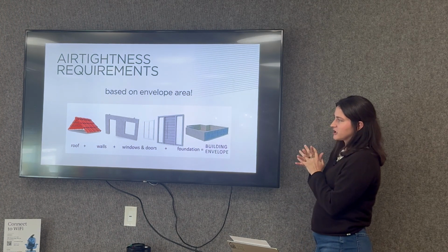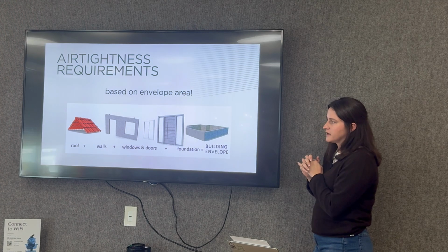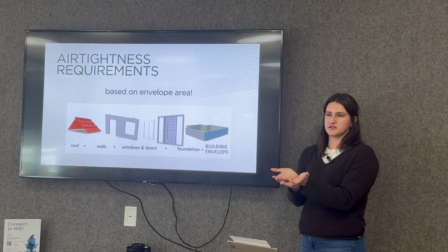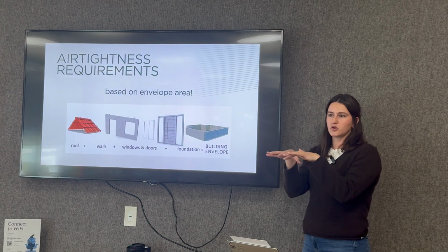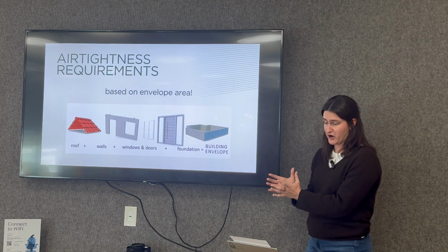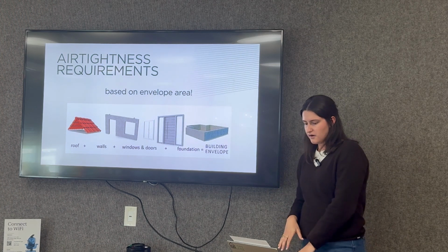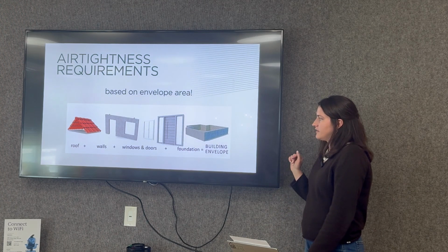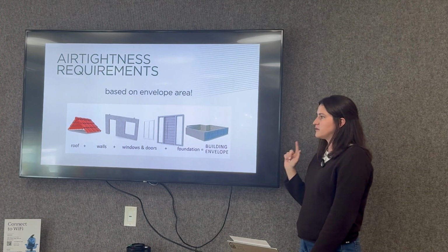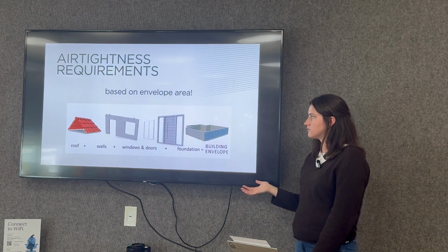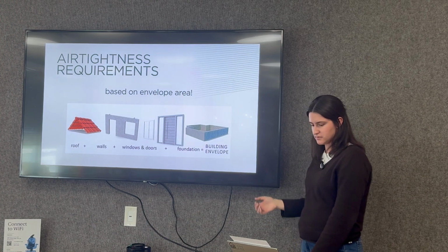The envelope area is a little bit different when you're doing compartmentalized, but essentially it's the same, super simplified. It's all 6 sides of the box. It's not floor area, it's not roof area, but it's the entire bubble of your air barrier. The resultant envelope area, which is agreed upon by the designers and the engineers, can then be multiplied by your minimum allowable air leakage rate, which then gives you a total value for allowable air leakage.